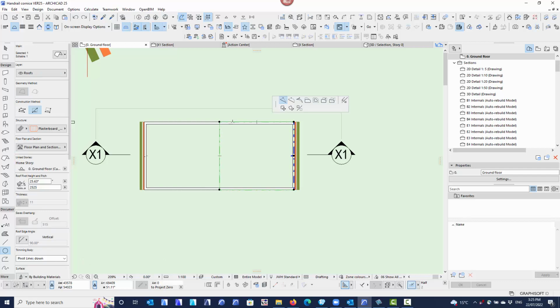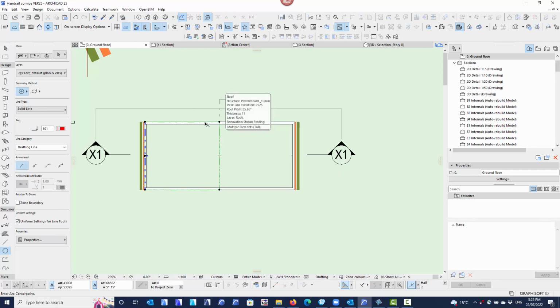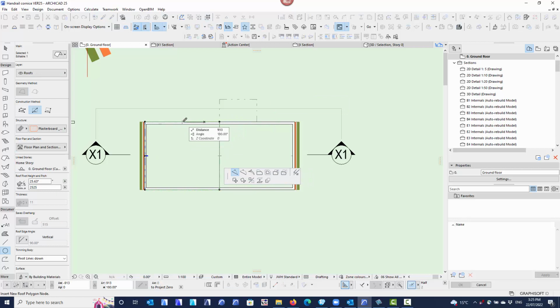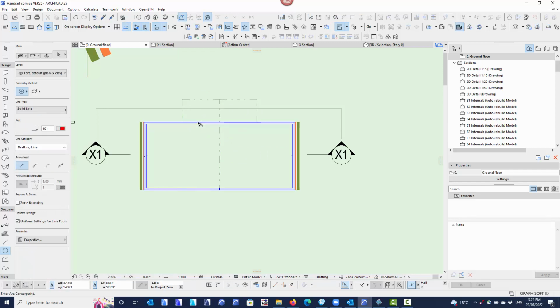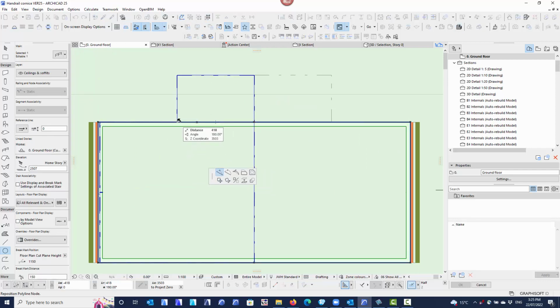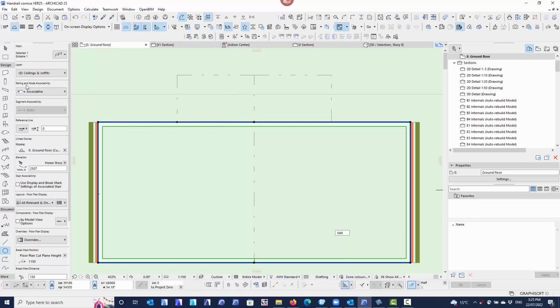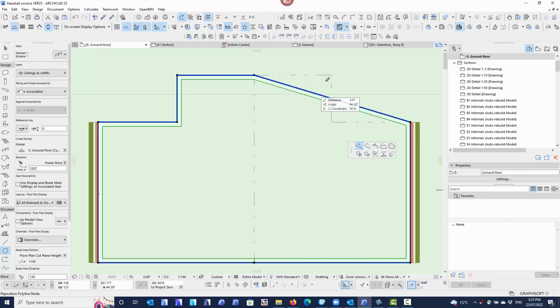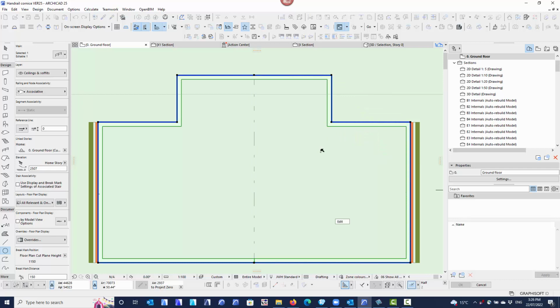So if I select the roof and I edit this roof so that I've got a little kick out, I'll select the other roof or ceiling and I add a node there. And I stretch that out to be exactly the same as that one. You can see here the railing hasn't followed, but what's really cool about this is I can now just grab this railing and say, look, add a node at that point there. Now that reassociates it, so it's become associative again. What I need to do is drag that node up to there. This node I want to keep, but move it to that point. This one I want to add a new node at the corner, and this one I want to add a new node at this corner here.